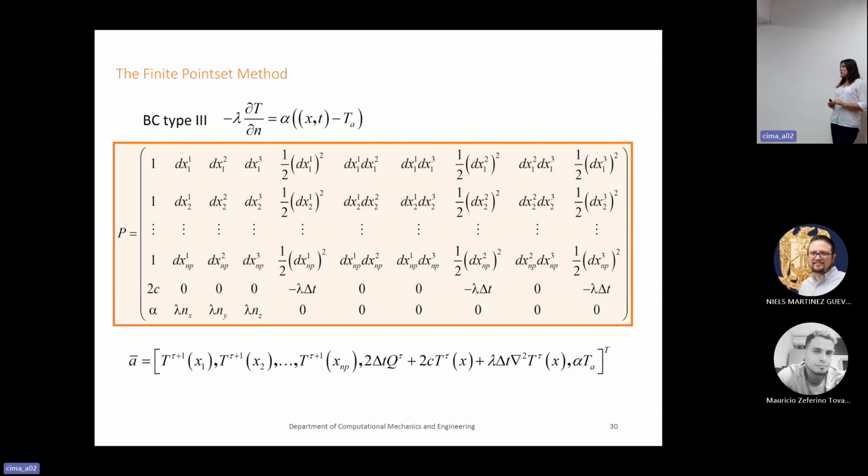If we have a boundary condition of the first type, we can apply the same approach, or also we can just put in an arbitrary way those temperatures on the boundaries and not recalculate them. Just use them to calculate temperature of other points, but we don't calculate them.